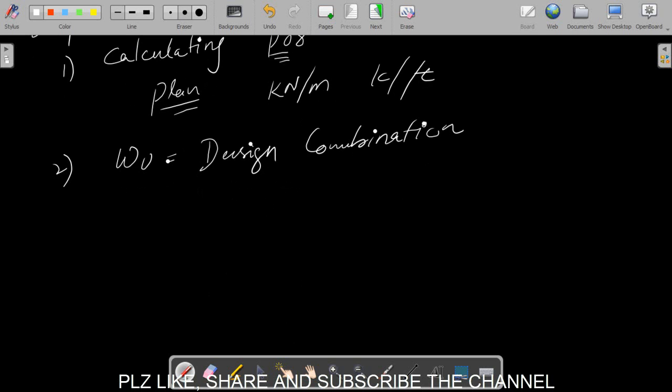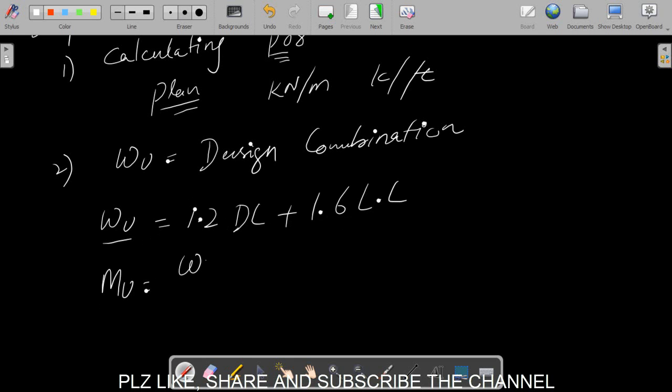For a gravity loading case, when we have no earthquake or wind, the governing equation is 1.2 dead load plus 1.6 live load. This is the governing equation. From this we then determine the ultimate moment, that is Mu. For a simply supported beam, Mu equals Wu L squared divided by 8.